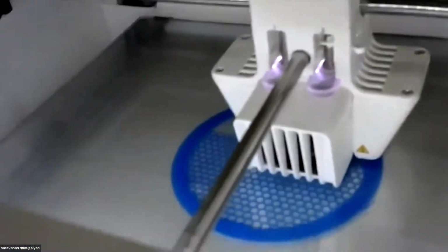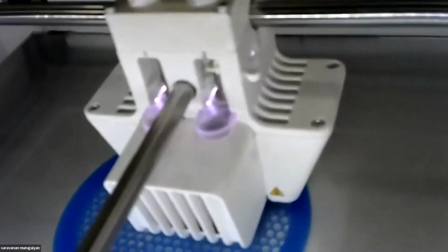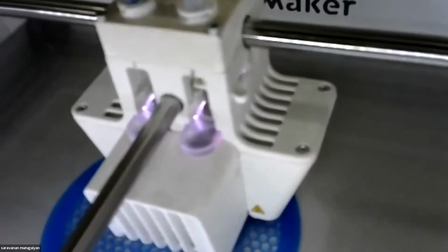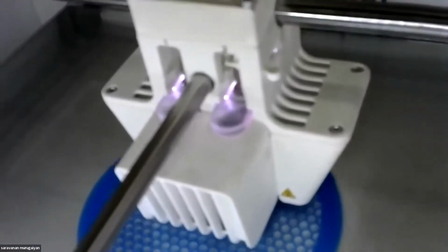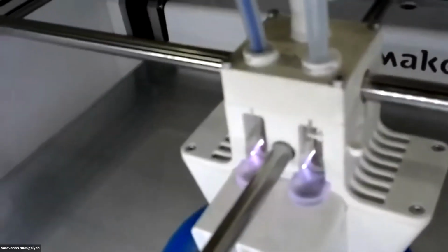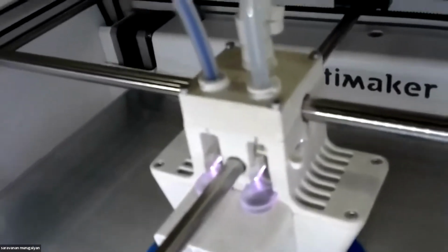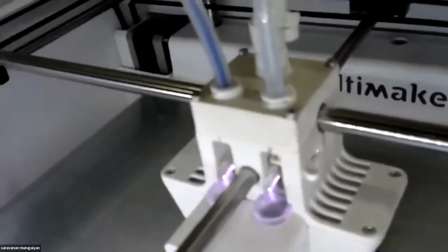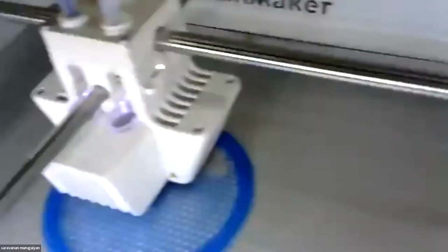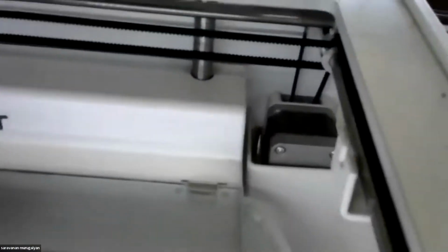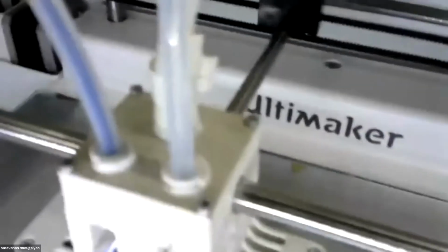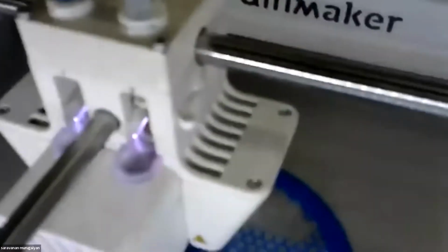And here, as you see, the extruder moves in such a way that it is fed with G-code data from the tessellated and sliced component that we fed in, and it is moved with the help of three different stepper motors, which actuate the movement of the extruder, and this prints the component on the whole.